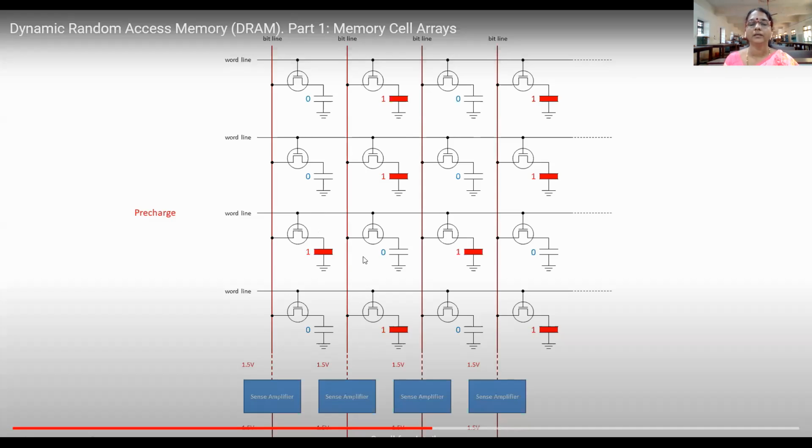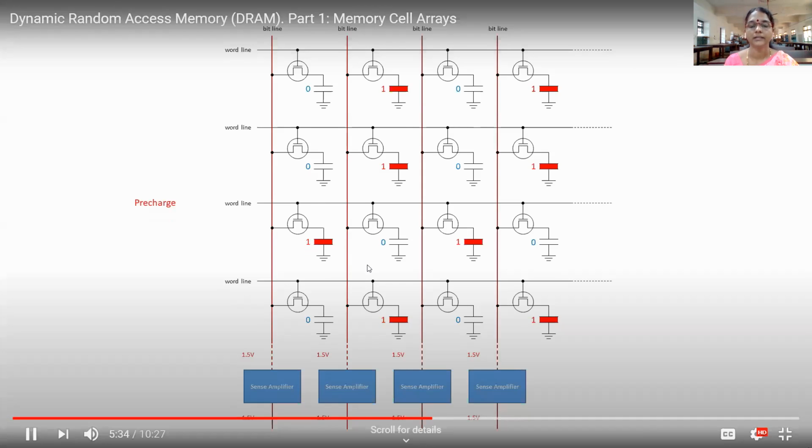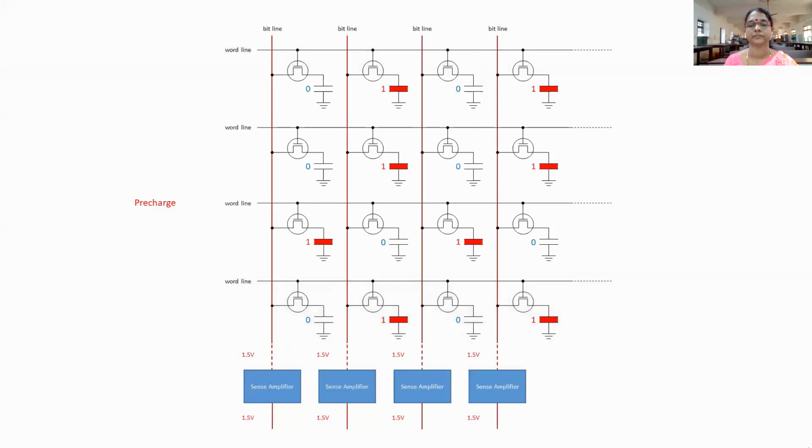Okay, next what happens? 3 volts. Each bit line is pre-charged to 1.5 volts above ground. This voltage is applied only very briefly, then it's removed. The bit lines are disconnected from ground, so they remain charged, albeit very briefly, rather like capacitors. We say the bit lines are allowed to float. Now, the word line is set to a relatively high voltage. The word line...